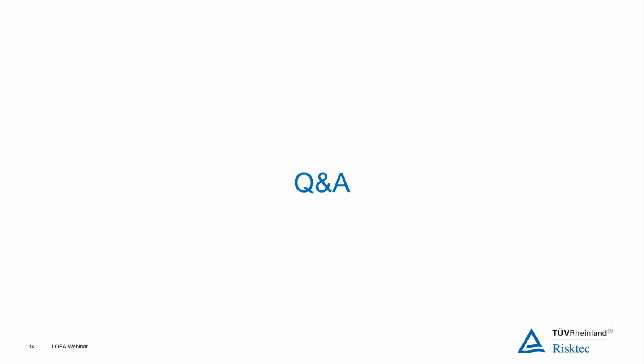Sorry, I was on mute there. Could you repeat that question? Sure. Are LOPA and SIL suitable for hydraulic systems, for example a hydraulic wellhead control panel, or would we use a different technique for something like that? Yes, the SIL rating tends to be something you apply to the actual electronic systems. But you can apply the principles of the methodology to a hydraulic system, certainly.